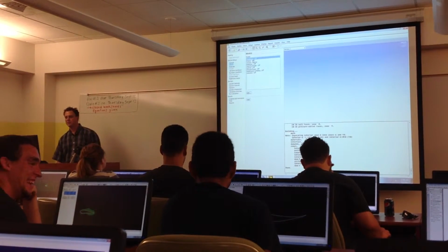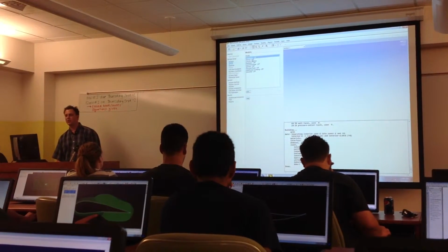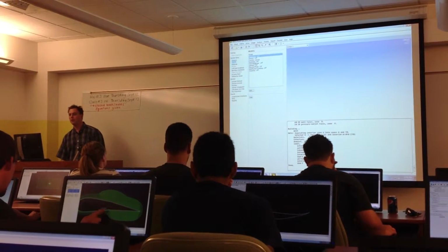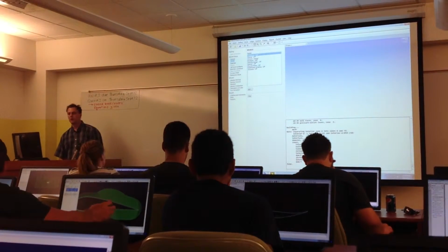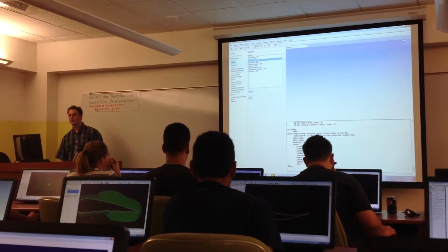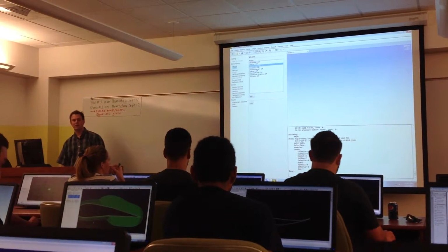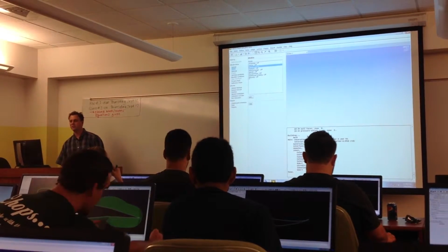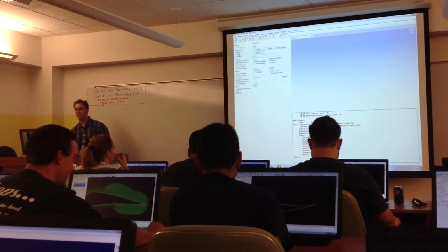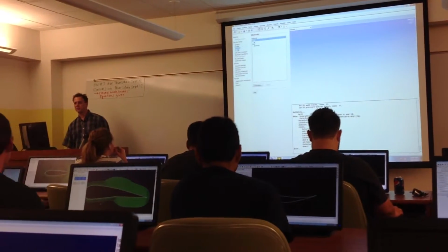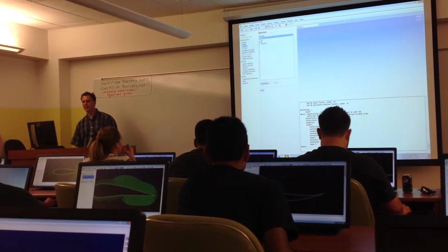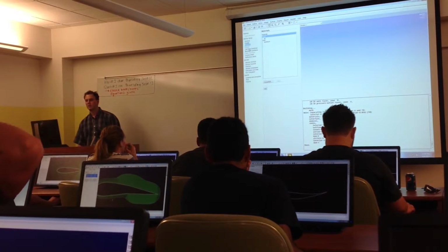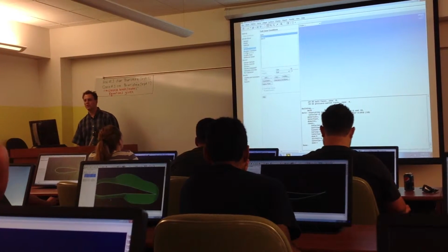Under models, we don't need any of these things. I don't need the energy equation because I don't have temperature variations to worry about. I don't have heating. I'm going to stick with laminar, not putting a turbulence model on for now. So all these things are default. I haven't changed anything at this point. Materials, the default is the air. Again, I'm not changing the material. Don't mess with cell zone conditions.